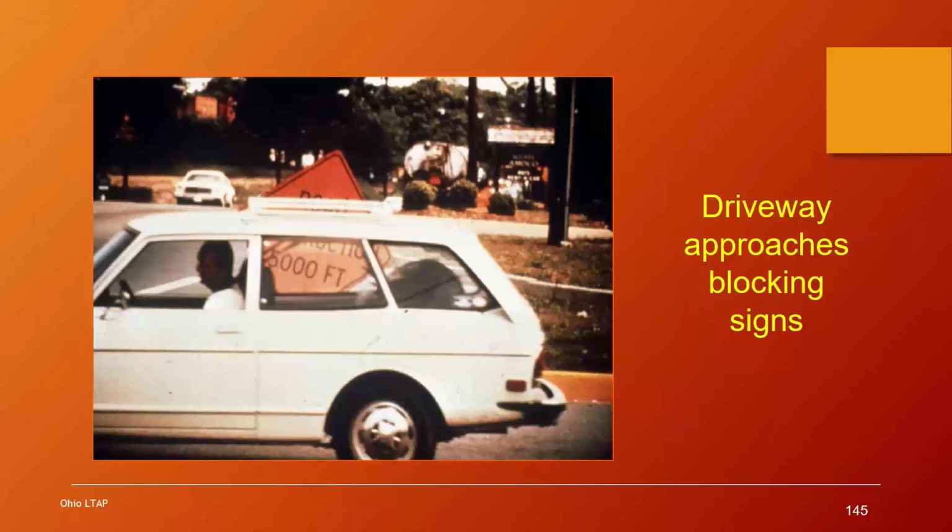So you can adjust that, either move it to the other side of the intersection, make sure you're not blocking sight distance of this motorist, or the other way. So you need to figure that out. You should be able to figure that out before you leave the garage to go out there and work, by using Google Maps, the aerial view and street view, and I'll show you how to use the distance measuring tool in Google Maps.